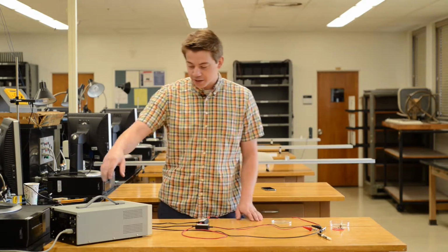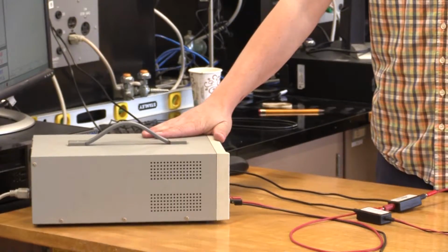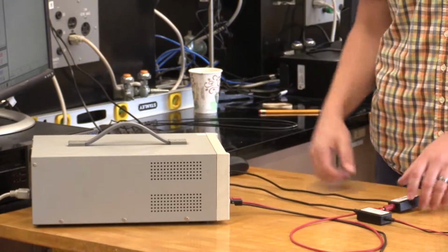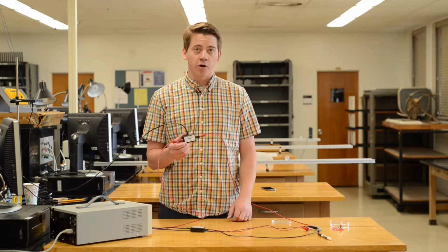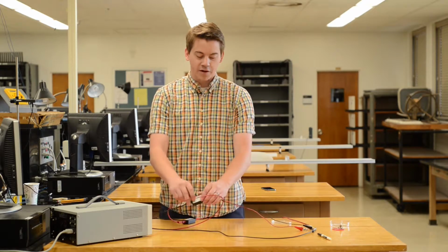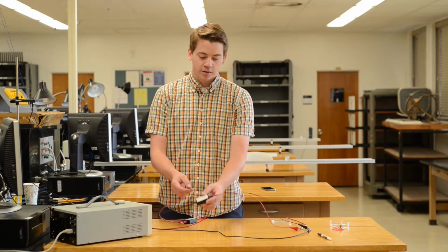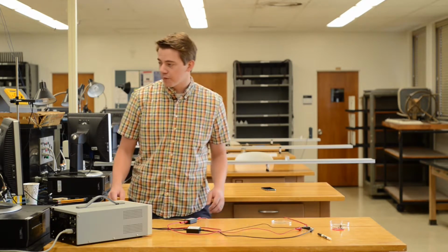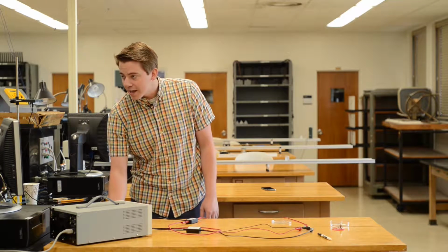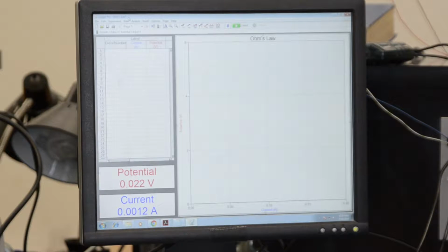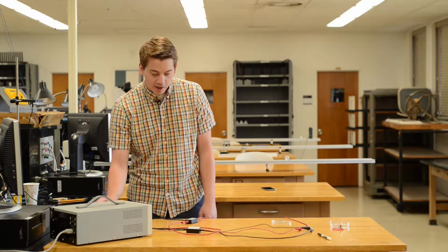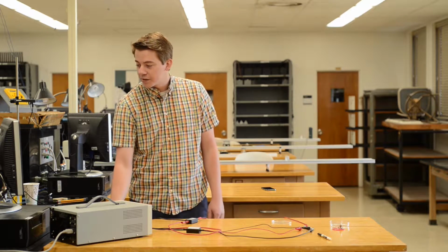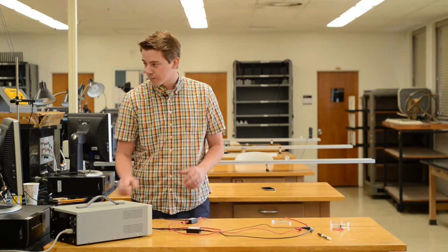The tools that you will need are a DC power supply, as we used last week, a Vernier current probe, as well as a Vernier voltage probe. So using the LoggerPro software, opening a LoggerPro file called Ohm's Law, students will be changing the voltage of their power supplies and collecting data points of voltage and current going through and across their resistor, respectively.